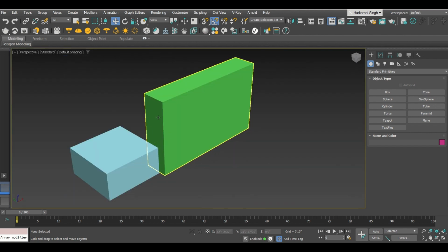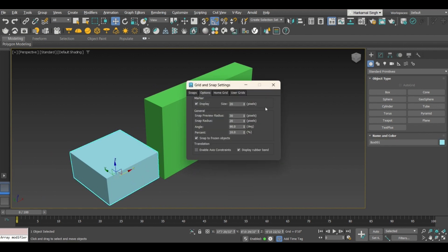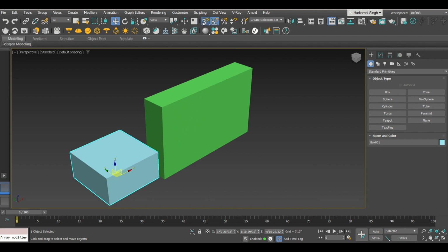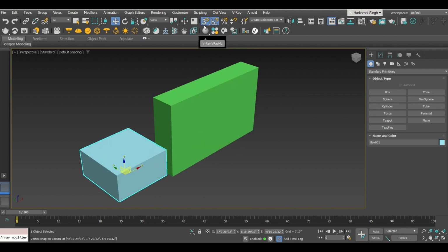Okay. So this is how we will be using the move command and rotate command, only after selecting these options, into the angle 90 degree, into this one, vertices. So whenever you are moving things freely, turn this off. I would recommend that.